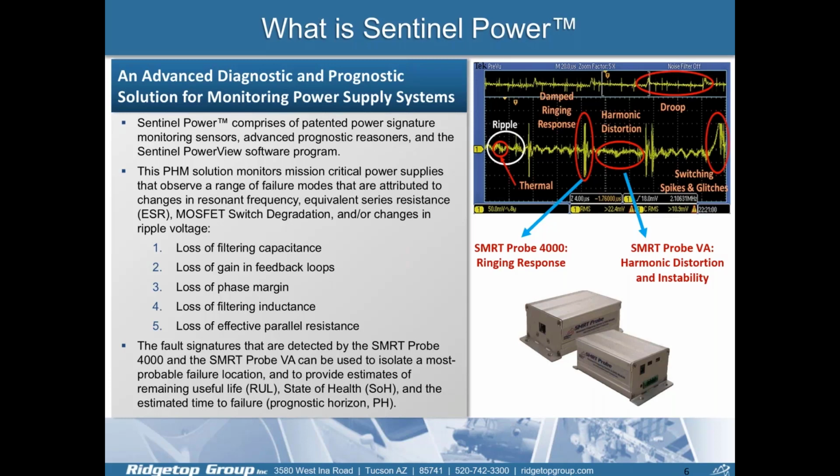Those losses are commonly referred to as failure modes. Failure modes produce very characteristic signatures. For example, a loss of capacitance in a filter circuit will normally produce a signature that looks like a square root function. A pi filter will normally produce a signature that looks like a convex increase in current or increase in noise. So those are very characteristic signatures, and we have identified 7 such families of signatures.